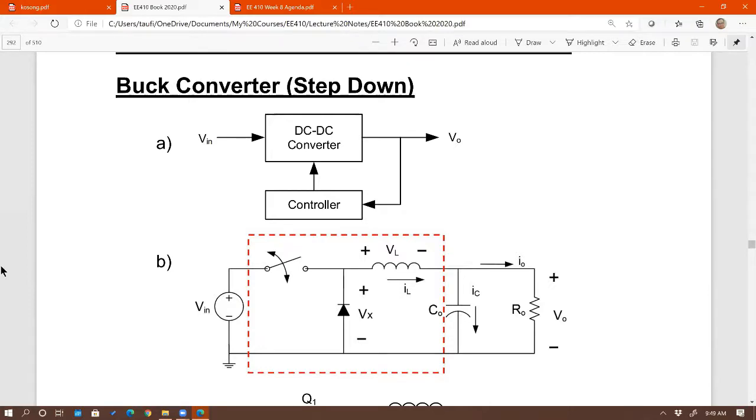Some of the sizing phase of the design is based on waveforms, so it is important for you to understand the different waveforms in the converter, because we use those to size components, as you will see. That's kind of the steps in covering DC to DC converters. Doesn't matter if it's buck-boost, push-pull, flyback, or forward, those are the steps that I'll be going through for each one. Okay. All right.